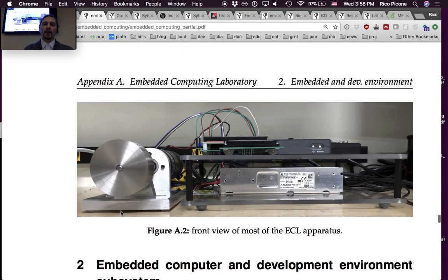Yeah, so you can't really see much different from this side other than just a little bit of a different view. There's some rubber feet, and you'll be able to tell once we start running the motors. When you start running these things, you're going to get some vibration, even though they're really well put together. Nothing is totally perfect. You always have some slight misalignment, so that always creates a little bit of vibration that gets transmitted from the motor down into the structure.